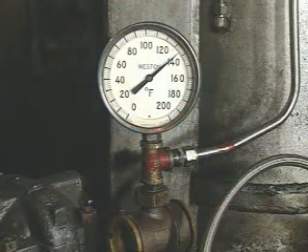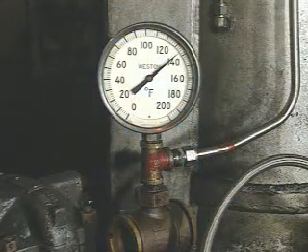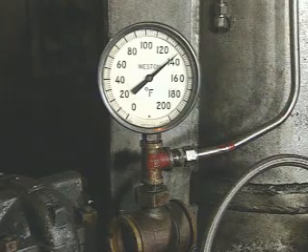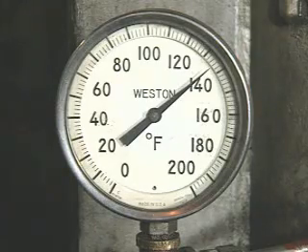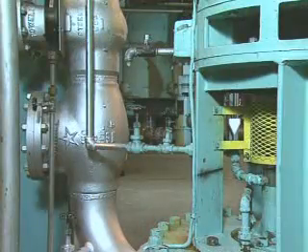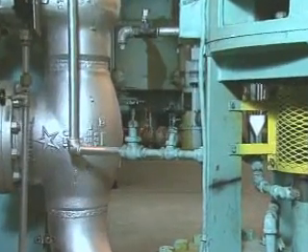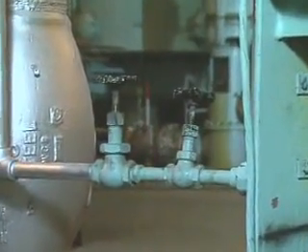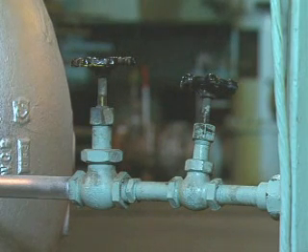For this pump, a gauge measures the temperature of the lubricating oil leaving the pump's bearings. If the reading isn't within the normal temperature range, there's generally a problem that should be reported. Many pumps use cooling water to cool the pump's bearings. When you check these pumps, make sure that the valves in the cooling water lines are open.